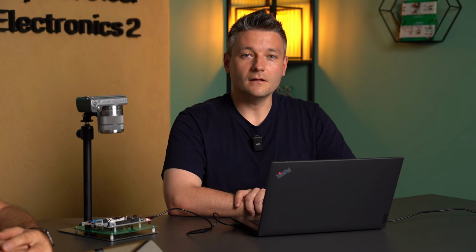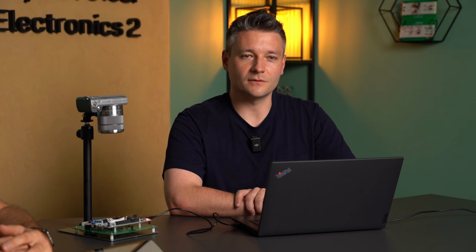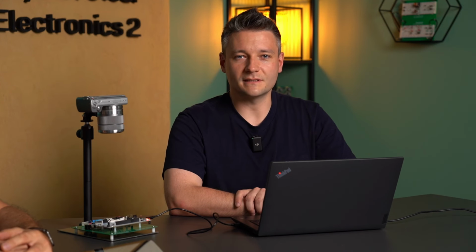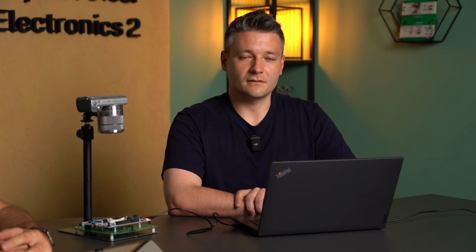Let's put the RTC peripheral of the F446 into use, for which we need to decide two things in advance. The first is the choice of the clock signal, because the RTC needs a basic clock signal, which is understandable because the RTC is kind of a timer module which can be driven from an external quartz crystal oscillator or from an internal source. On the development board, the first type, an external quartz crystal oscillator, has been incorporated.